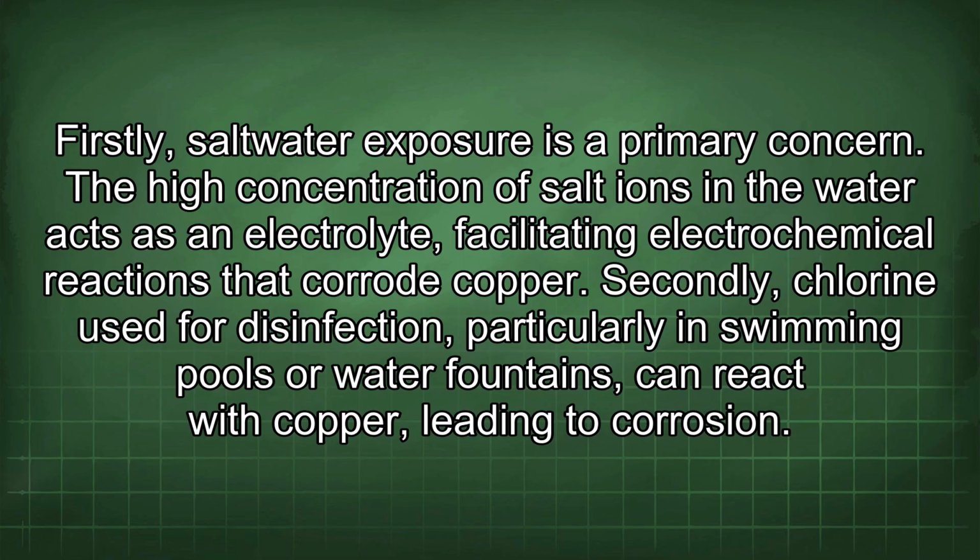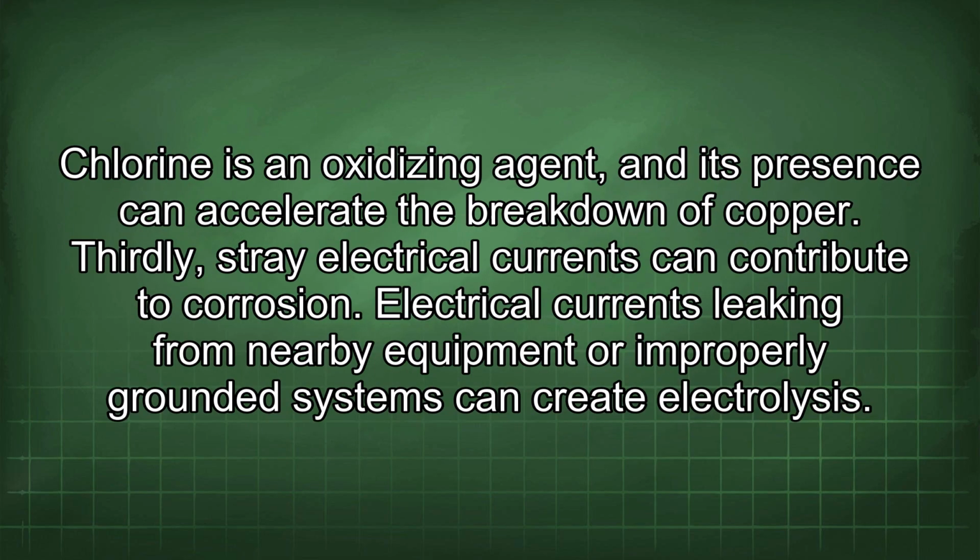The high concentration of salt ions in the water acts as an electrolyte, facilitating electrochemical reactions that corrode copper. Secondly, chlorine used for disinfection, particularly in swimming pools or water fountains, can react with copper, leading to corrosion. Chlorine is an oxidizing agent, and its presence can accelerate the breakdown of copper.